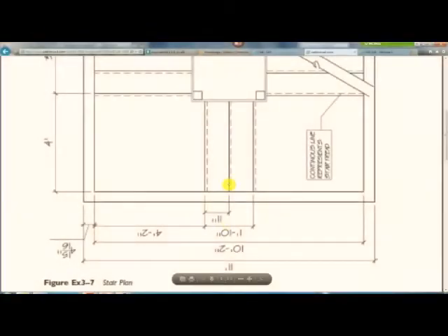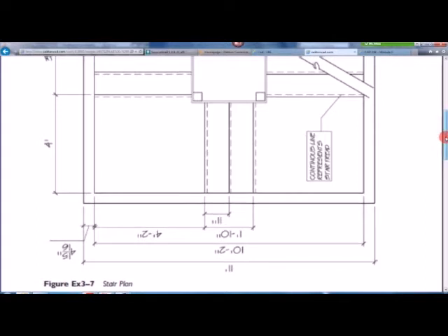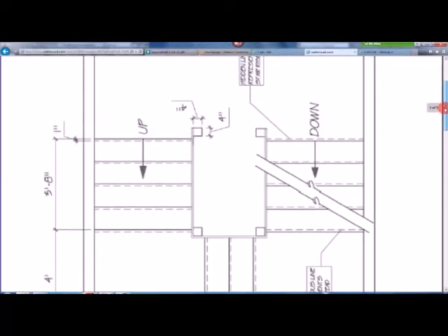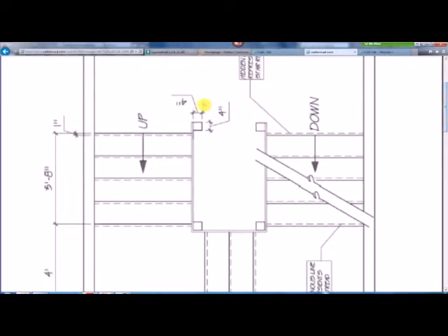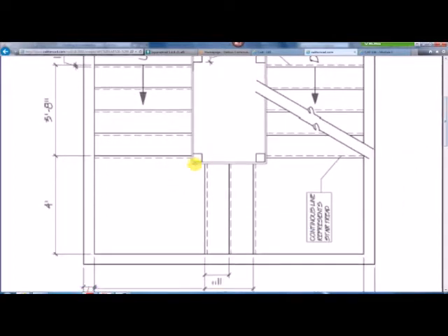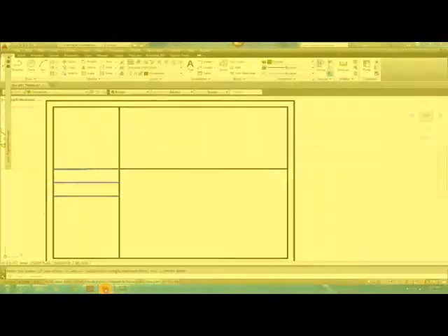So we're going to take a look at the drawing here. And it's a symmetrical drawing. And so there are some dimensions that are missing on it, but essentially what we're going to do is we're going to put in these 4" by 4" posts, and we're going to make a 1" retainer here that goes around these posts. And what we can then do once we have this part drawn is to mirror it over to the second half. So getting back to AutoCAD.